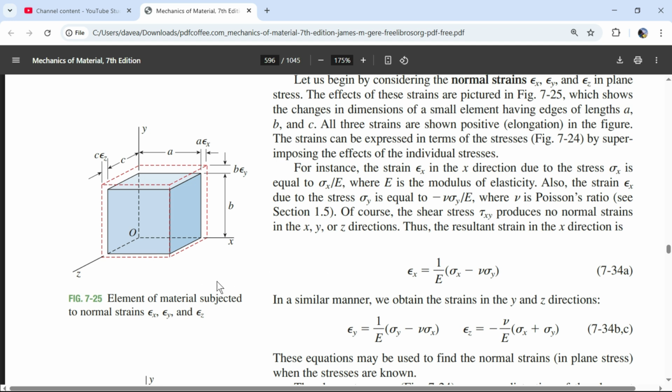So at least that has, but any numbers that are less than a tenth, I think is difficult to kind of wrap your mind around. Anyway, so we got that strain is very small. And how do we relate 0.002 with 58,000? Well, the equation to relate them is y is equal to mx, the equation of a line, or 58,000 is equal to 29 million times 0.002. 29 times 2 is 58, and then 29 million times 0.002 gets the job done, and we get 58,000.